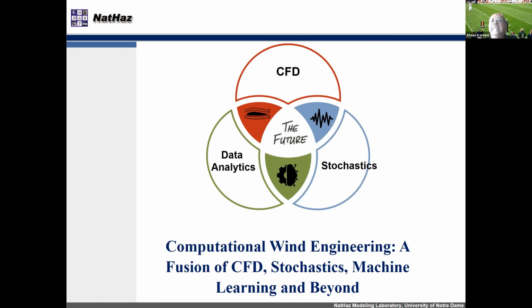So there are other techniques becoming available in CFD which rely on data analytics or machine learning, and some part of that is stochastic emulation of what happens. One of them is multi-fidelity modeling. For example, one of my students is simulating things using RANS, which is very fast and quick. And she is developing a bridge between large eddy simulation and the RANS results, which are more quickly obtained. This type of bridge is some sort of surrogate modeling or machine learning, which helps us develop that, and she has shown a lot of success.